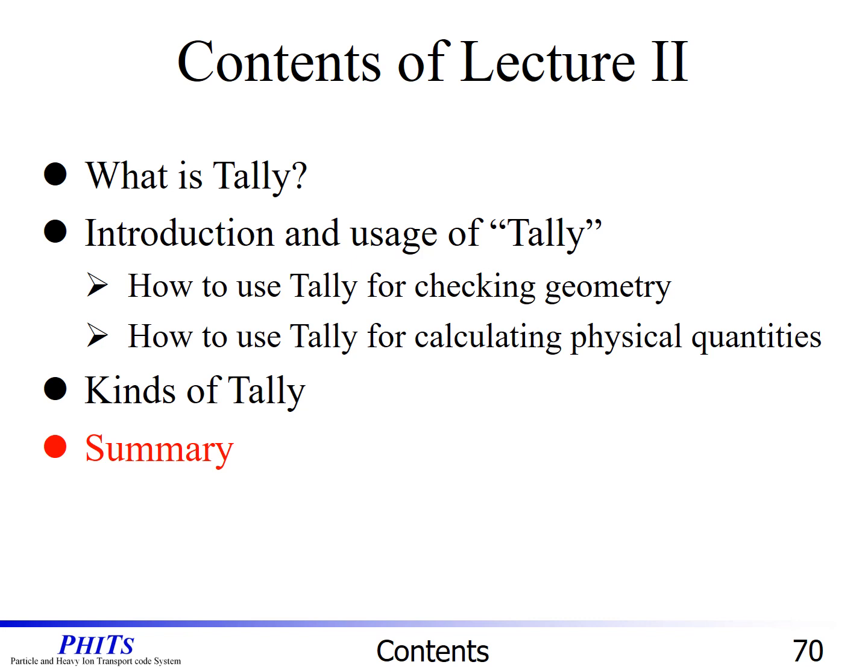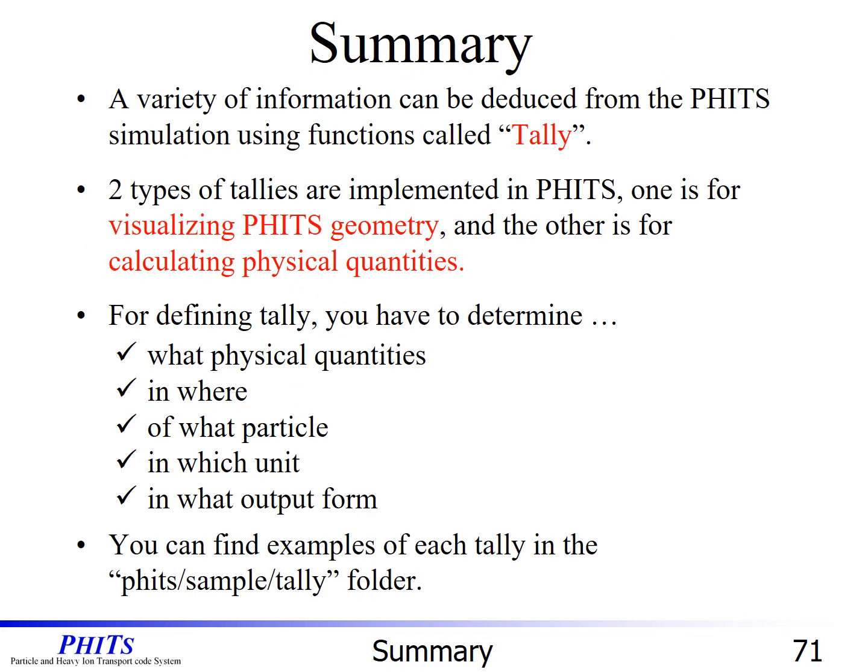Let me summarize the basic lecture number 2. A variety of information can be deduced from the PHITS simulation using functions called tally. 2 types of tallies are implemented in PHITS. One is for visualizing PHITS geometry, and the other is for calculating physical quantities. For defining tally, you have to determine following components. You can find examples of each tally in this folder, so you can copy and paste tally section from them.